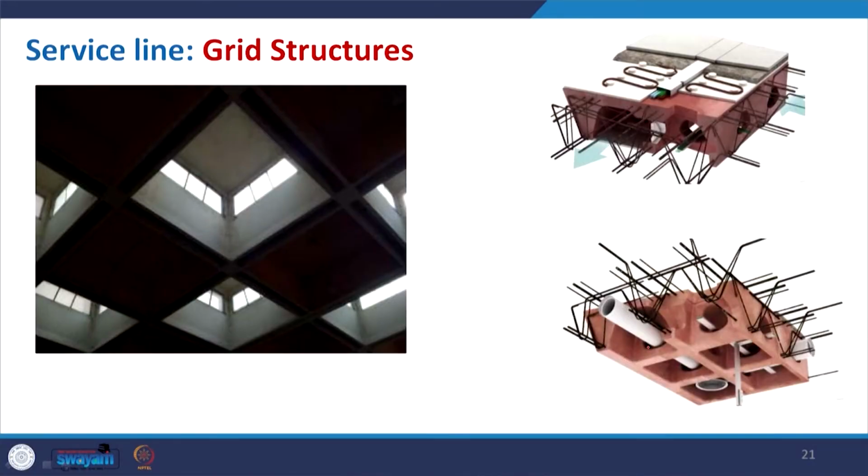Now, aligning the services is very important for the flat slab. We also put the reinforcement, and then we try to make a false ceiling to cover it. But because the waffle slab has depth, and sometimes if that can be done with the mold and especially designed for it, then all the services can be fixed within that. So, this is one example where the pipelines can go, and here also you can see the electrical fittings, how they can be adjusted within that section.